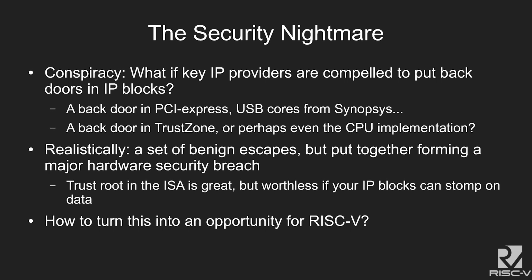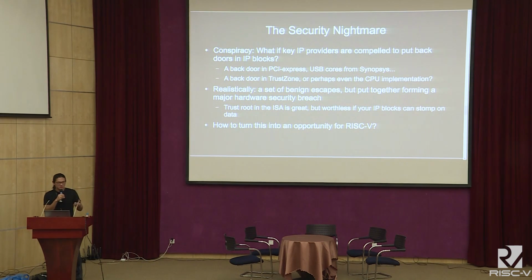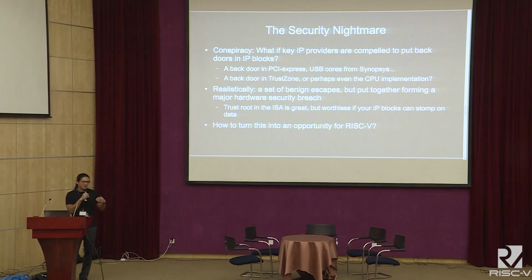TrustZone, for example, makes some very big assumptions about the memory subsystem being intact. If anything along the path, say a crossbar switch or a DDR controller, has a test escape that allows you to suppress a write or swap the order of bits, which is actually pretty common for DDR buses, and it's not a documented feature and you haven't locked that down, then all of a sudden you have a big problem in the wild: a pretty powerful rootkit that you can install on almost any device.